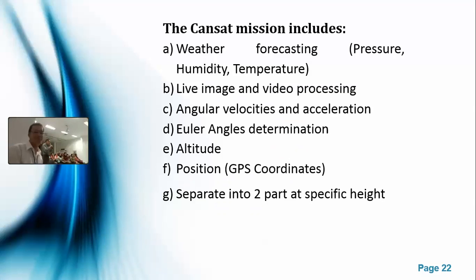Now, talking about the separation system. In the CANSAT competition of Texas, the specification required a two-part CANSAT. Firstly, one part separates from the rocket, then the second part separates at a height of 500 meters. The upper part used a parachute to land on the Earth with a 12 meters per second falling speed, while the second part landed at 10 meters per second without using a direct speed drop like a parafoil, parachute, etc. While in the RLS competition, the case is different, with more specifications.